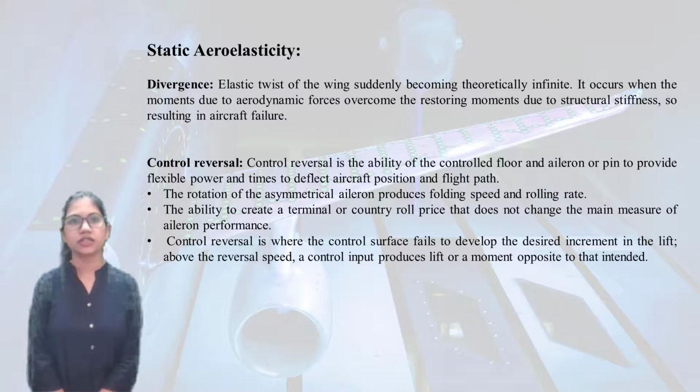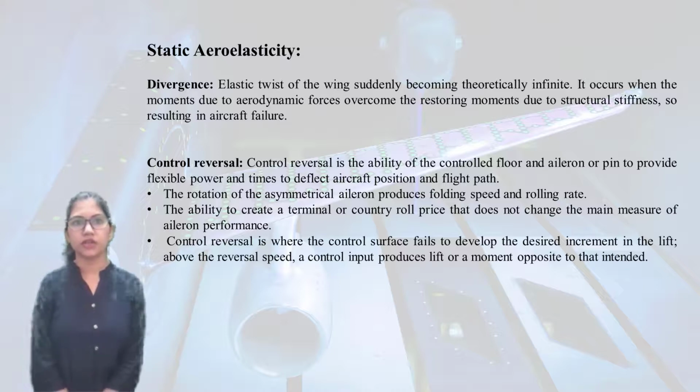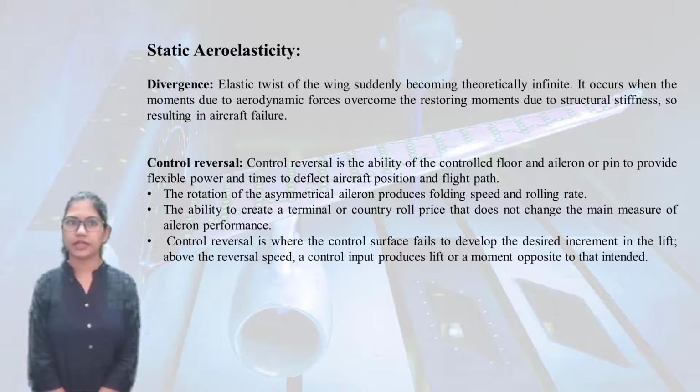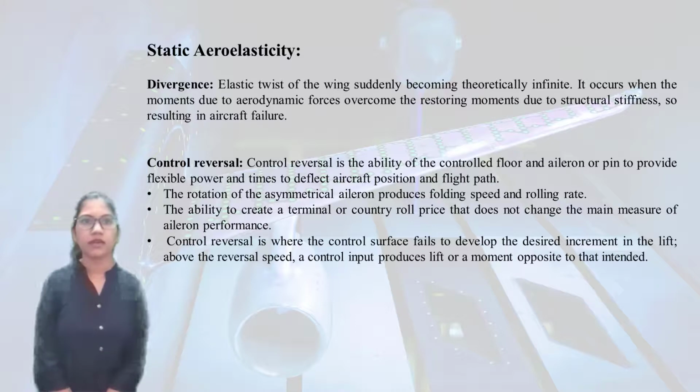In general, this reversion may occur on any control surface. However, it is typical for the lateral control system, that is the aileron, because the ailerons are placed in the tip region of the relatively flexible wing. Another, but highly rare, option is the reversion of the elevator due to the low stiffness of the fuselage, which may occur with unconventional aircraft with tail booms.